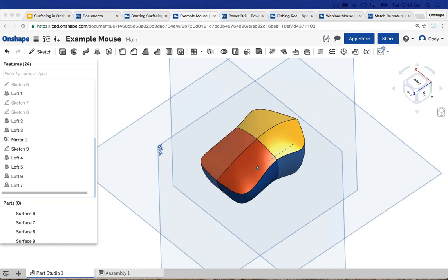What exactly defines a guide in a loft edge? Well, it's really more of what you click on, in the examples I've shown you up to this point, it's more of how I define them. They're in 2 different boxes, so to speak. In some situations, they're almost interchangeable. In some situations, I do want to stress that, not all. So the examples I've shown you, in some cases, they could be interchangeable, but in many situations, it's the guide that manipulates the transition from one contour to another.